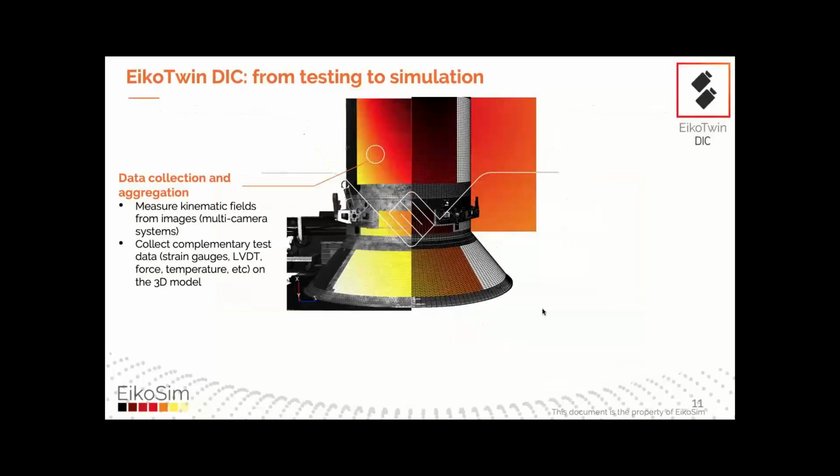The first software we've developed here is EikoTwin DIC, which is image processing and test data management software. It relies on optical measurements, as I showed before. I'll show right after how it works. But the idea here is to align the mesh with the images that are taken by cameras during a test in order to help with image processing, measure displacement and strain fields, meaning a lot of data points with respect to traditional point-wise sensors.